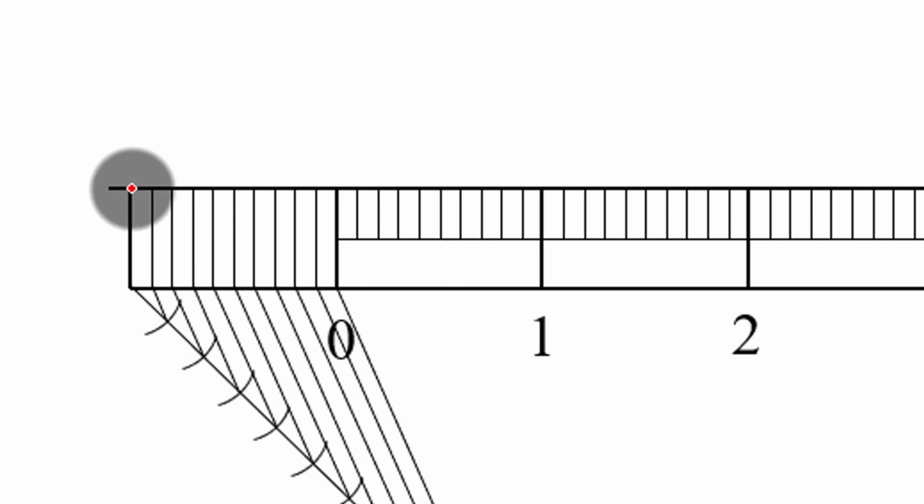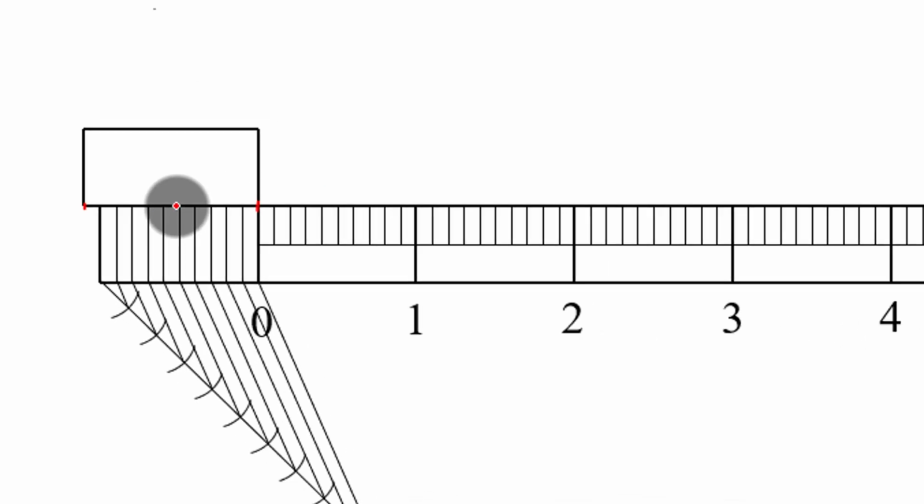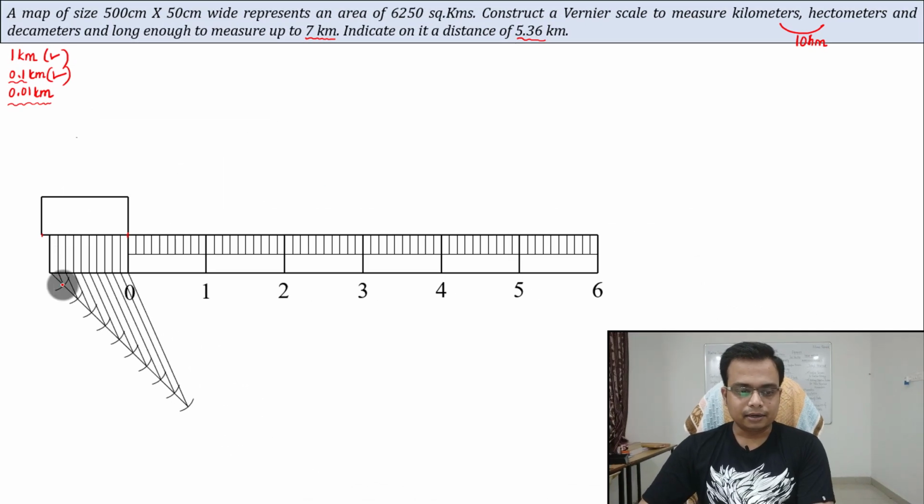So you can keep your compass over here while the pencil end is going to be here, and then you can make an arc, and you'll have this division equal to this division. As simple. Then produce lines from this point and from this point in the upward direction. How high? Well, 10 millimeters. That will do the job for us. Done. Again, how many divisions did we do over here? 10 divisions. In the same manner here also we are going to go for 10 divisions.